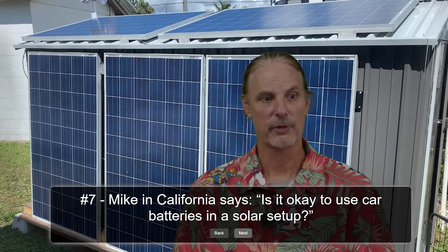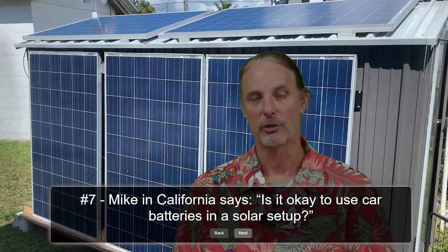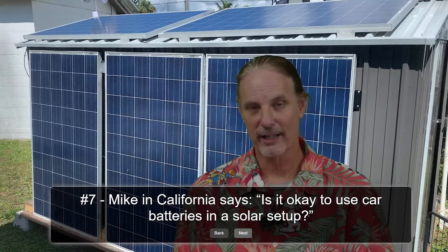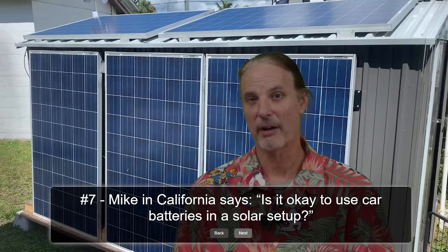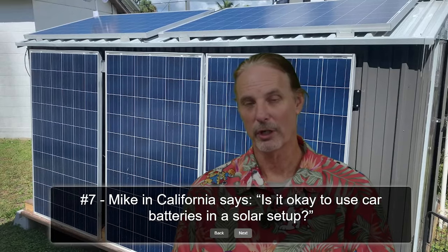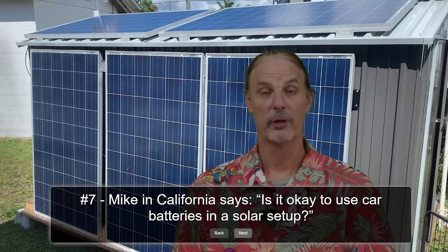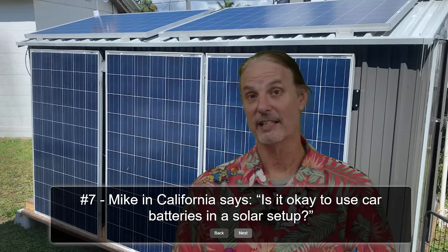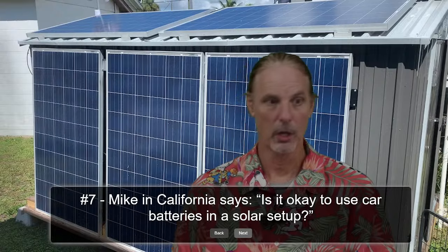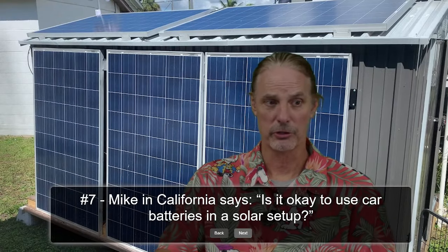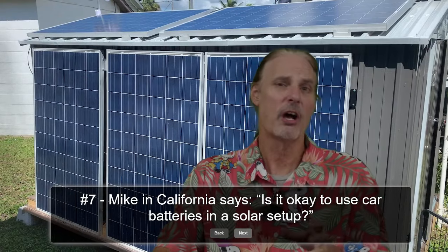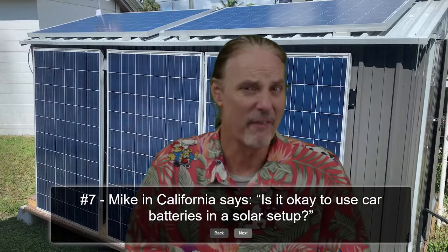This isn't much different than your car battery. When you leave your headlights on too many times, you damage the battery in your car, and then it doesn't work anymore, or it doesn't work as well, or it goes dead even easier and faster the second time. And by the time you do it 3 or 4 times, the battery just won't work anymore. And the same thing's true for solar systems. So you got to be very careful to shut off early, and that means above 50%.